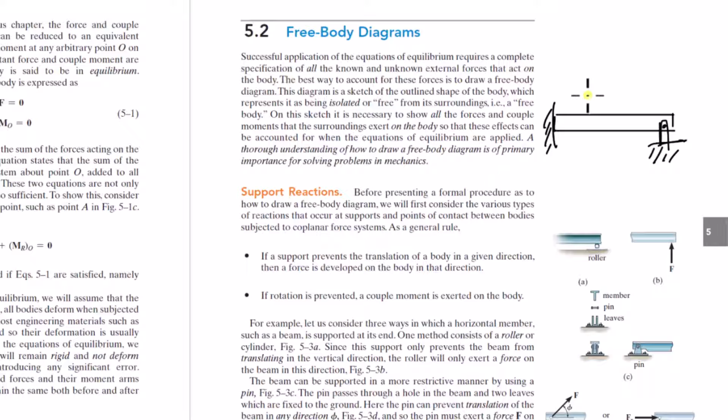But let's say you applied a pure non-twisting force, but then you decided to push on the beam a little bit on one end and then kind of pull it on the other end. In addition to some linear force, you also tried to rotate the beam a little bit. Well, if you separate out the components of that, some of that force is going to be a pure linear force, but then some portions of it are an equal and opposite force separated by a distance. It's a twisting, a couple moment, right? You can separate that out into some of this force is like this, and some of this force is like this, and you can turn that into a couple moment.